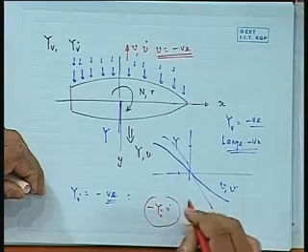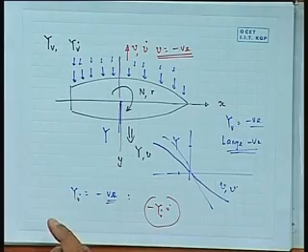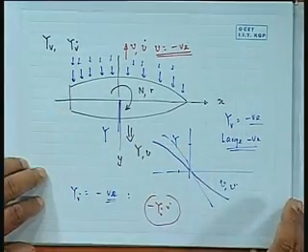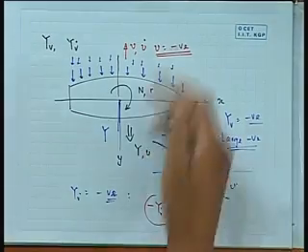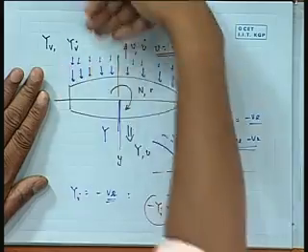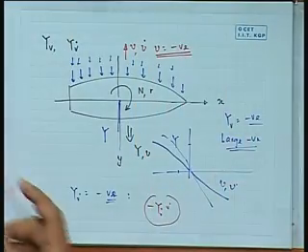This is like added mass into acceleration, and added mass in sway and surge are of the order of the mass. Why are we considering v and v dot as negative, sir? No, it can be positive. Because I gave an example where if I give a negative v dot, then I get a positive Y. If you give a positive v dot, you will get a force on the other side.